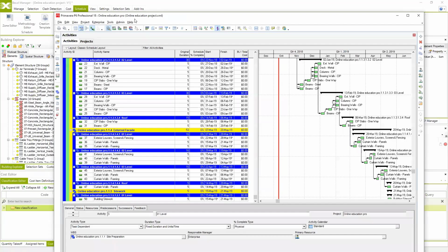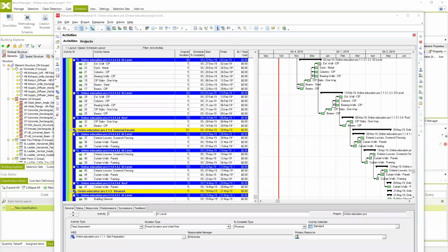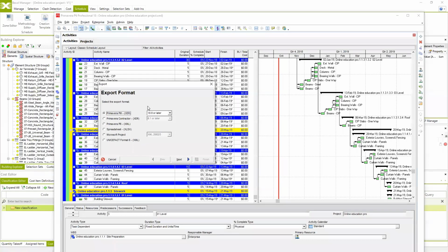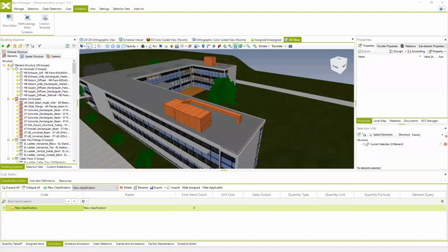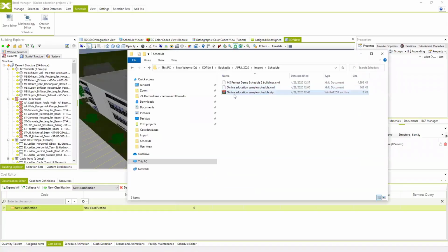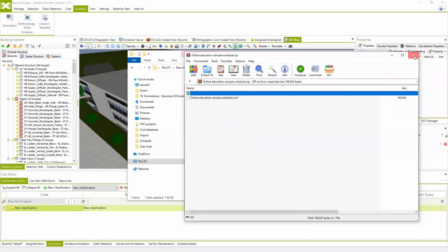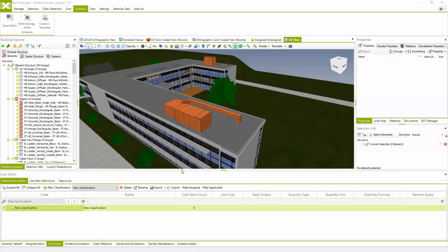And then using the export button for Primavera, we actually exported this into the XML files. And I'm not gonna waste more time doing that. Actually, I'm just gonna present you this same schedule, which is exported into XML file. Well, basically, when you export Primavera files, you're gonna get the RAR, or actually zip file, containing that XML file. So when you extract it, this is the schedule, and I'm gonna import the schedule in the BEXEL Manager.